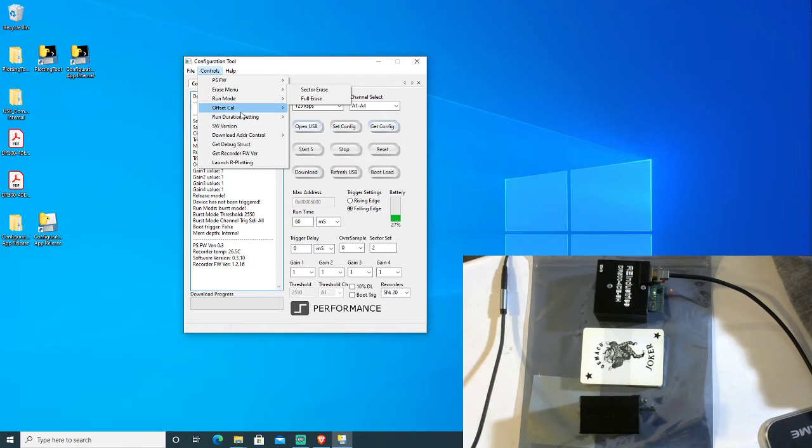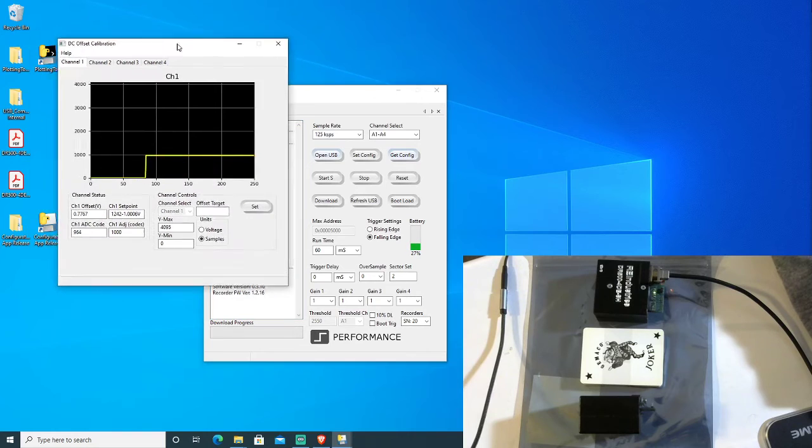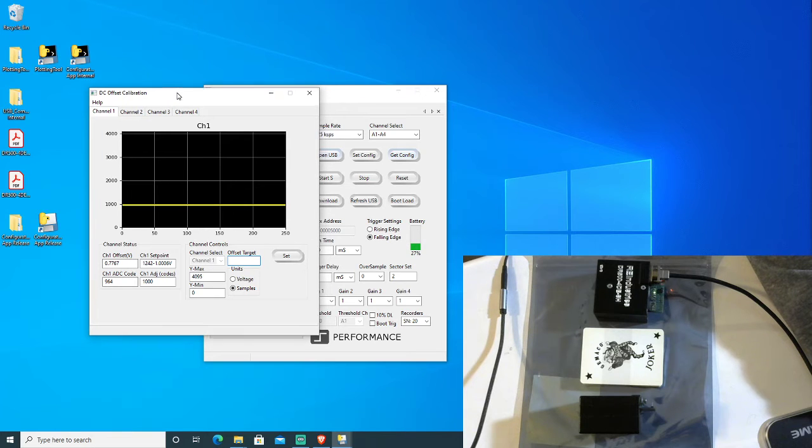One of the big things that stands out with this data recorder, though, that's extremely nice is the offset control. The DC offset control for these products, we have a visual display here with a few samples per second to give the customer a visual display of what's happening on that channel. This is generally used for calibration, so sensor biasing will move your DC offset, especially with a bridge, because it's usually around half of your biasing voltage. So this allows customers to visually walk the DC offset up and down from a software interface.